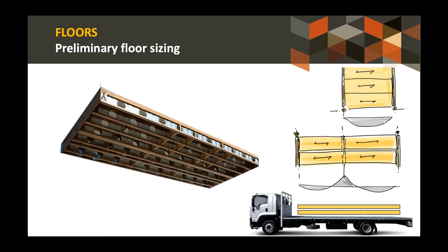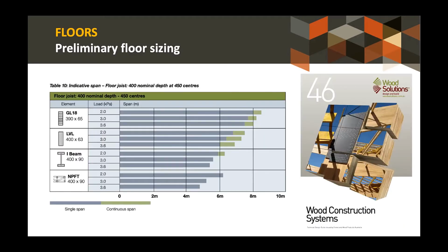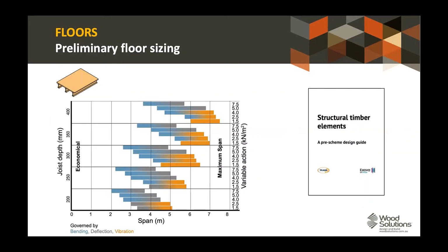So where's our first port of call for prelim floor sizing? Well, Wood Solutions has a great design guide here, Design Guide 46, which looks at wood construction systems. And in there are all kinds of different lookup tables for these preliminary design decisions, which allow you to marry imposed load and achievable spans. Apologies to Wood Solutions, but here's another reference. This is a really good one from the UK. This is published by Trada. And this does something similar, albeit in a slightly more graphical form.